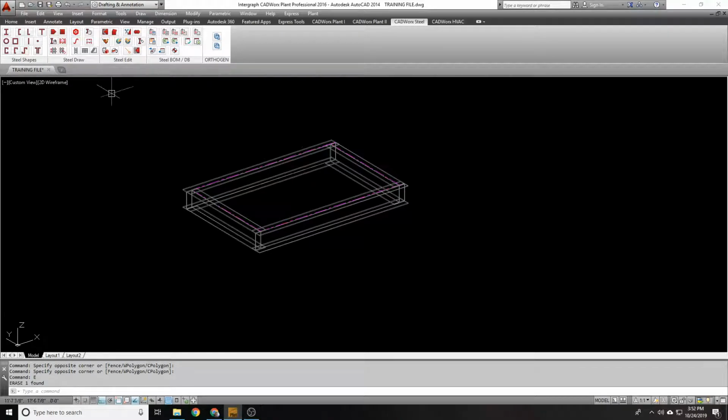The ladder tool is extremely convenient and honestly does a pretty good job of drawing ladders in. Having to model a ladder manually would be a huge pain. And CADWorx ladders actually look good. They fit their purpose and their function. They can be caged or non-caged. If they're caged, they can be right exit, left exit, or step through.